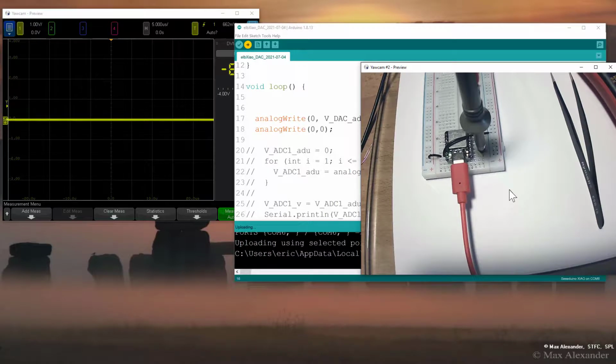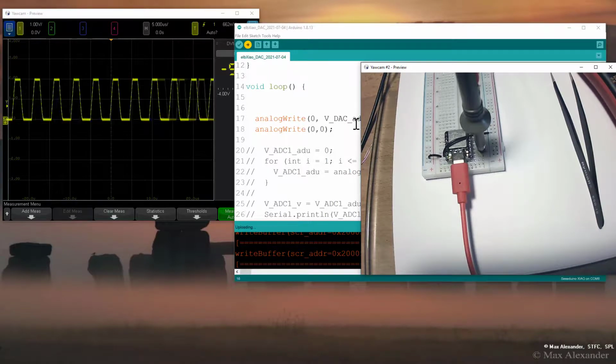So it's easy to sometimes get it to brick. One way of doing that routinely is to put no interrupts in there. That will get it to brick for sure. But it's also easy to unbrick it. It's just shorting the two reset pins together twice in rapid succession, and that automatically unbricks it. But just be aware of what the condition was that bricked it. So far, I've only found the interrupts that does it.